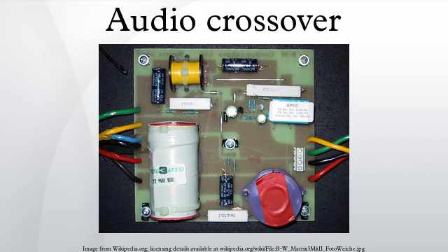Fourth-order filters have an 80 dB decade slope. These filters are complex to design in passive form, as the components interact with each other. Steep-slope passive networks are less tolerant of parts value deviations or tolerances, and more sensitive to mistermination with reactive driver loads.